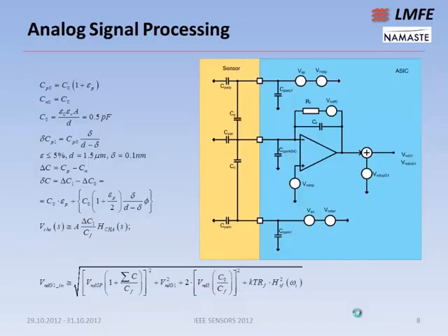Again, I will not go into the details, but besides the sensor, this is the most sensitive and most important part, which actually determines the sensitivity of the whole system. It's this transimpedance amplifier where most of the important noise sources in the system are presented. Of course, you can see the most dangerous one is this one, and we can analyze their contributions. The biggest contribution is this one, and it is even amplified by the ratio of this capacitor over the impedance of the whole sensor.